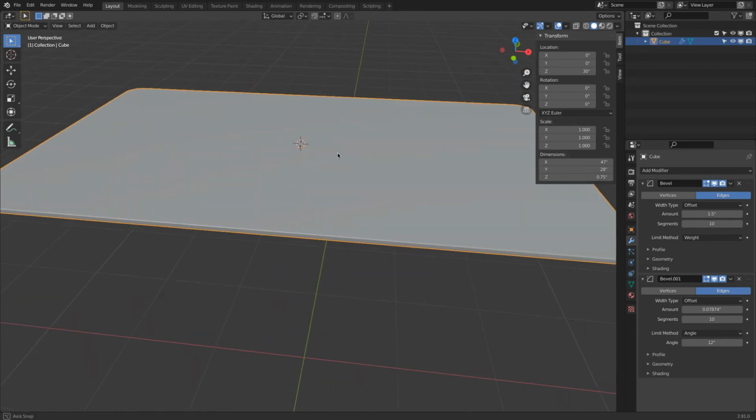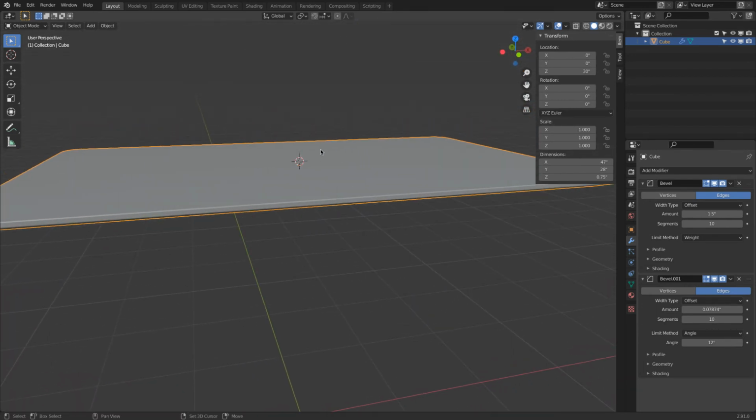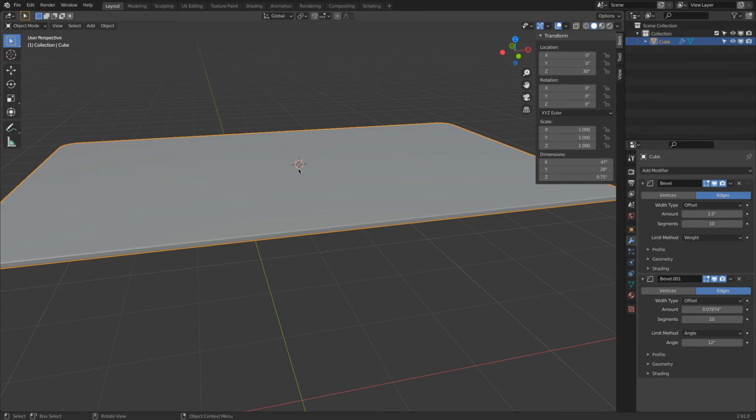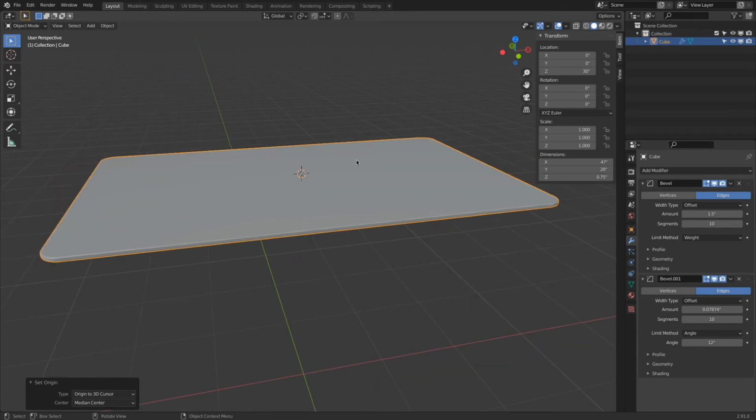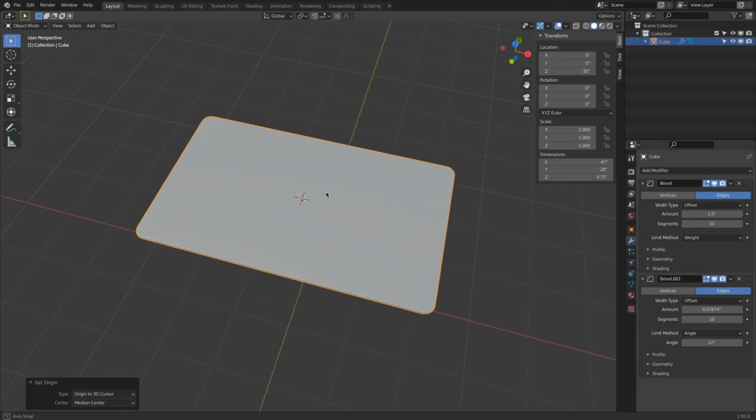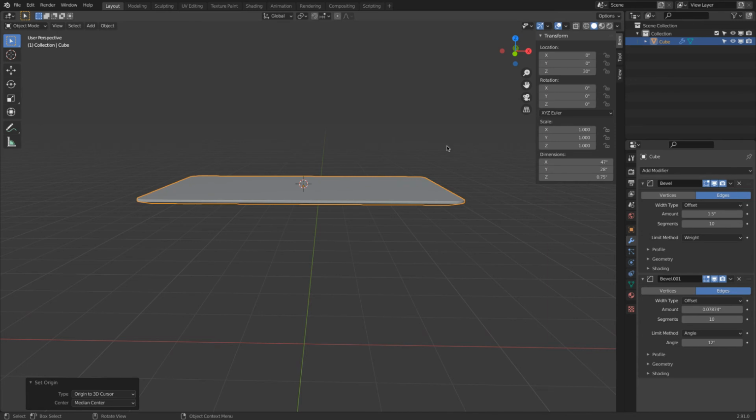So I zoom in a little bit so you can see how this center point will jump right to where the cursor is. There. Now this reads 30.375. Let's set this to just 30. And our tabletop surface is really at 30 inches now.